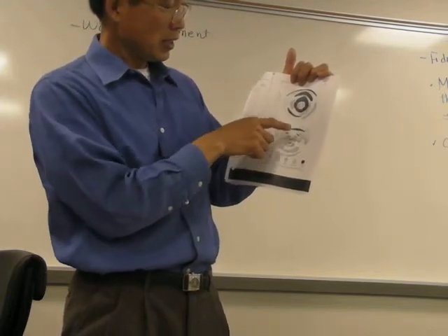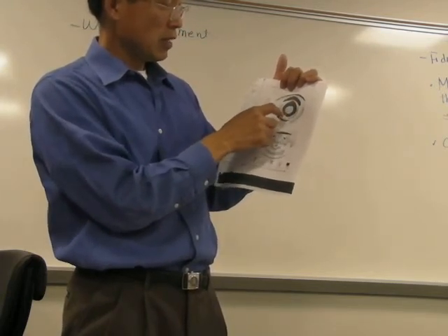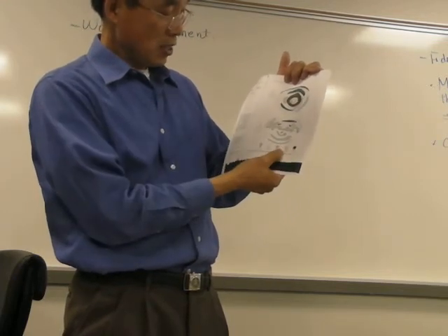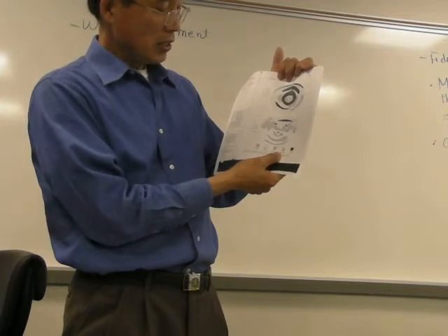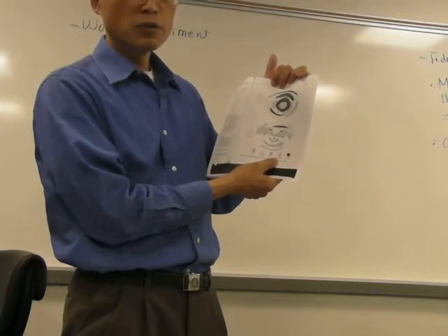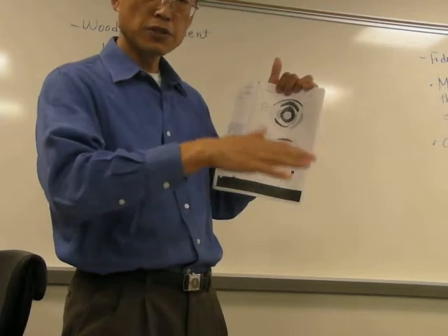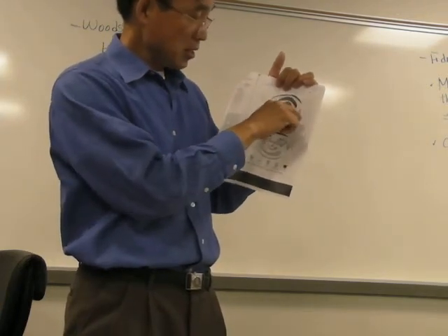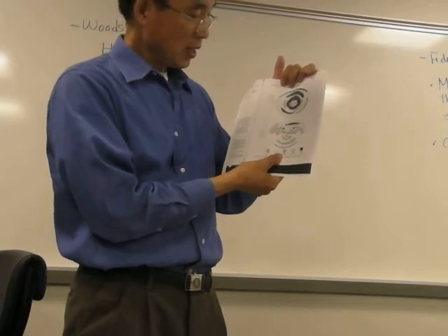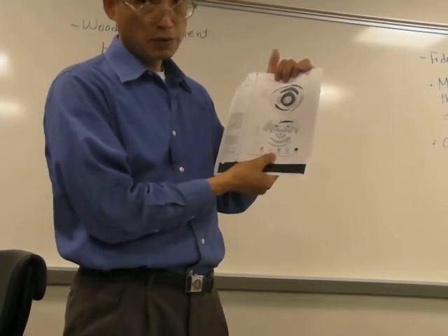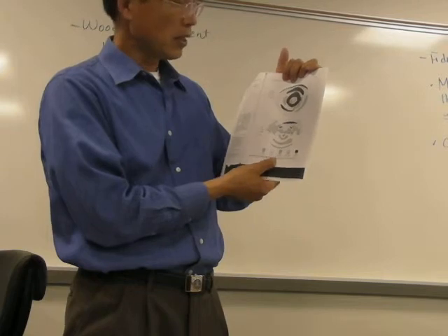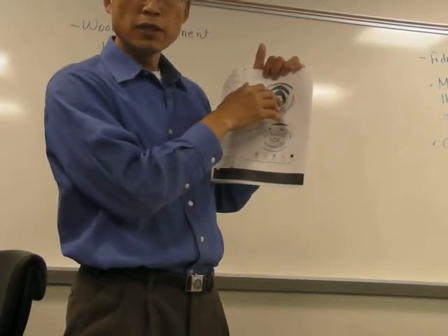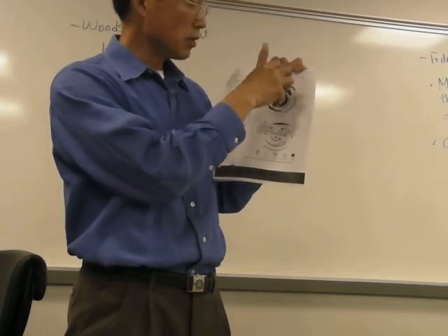And there's also the dotted area, which may look like sand, where the ARF is 0.25 to 0.125, also substantially reduced amplitude. And the hatched area has ARF 0.5 to 0.25. So you can see the amplitude can be cut down by installing those trenches.